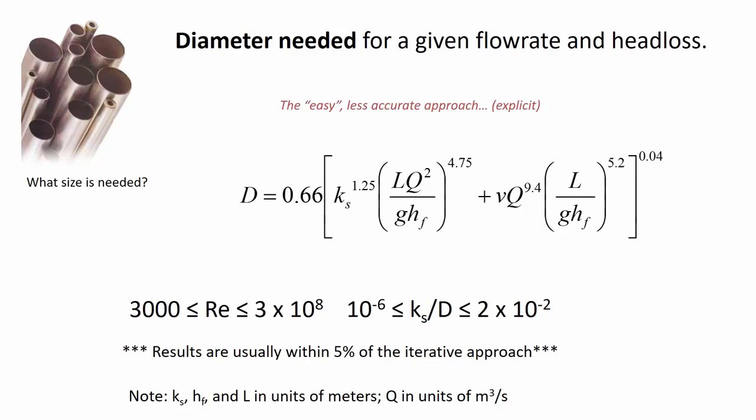Solve this formula. And it's really tough to get through it without accidentally punching in the wrong number in the wrong spot. But let's give it a shot. We have, for this one, the explicit equation. Remember, the roughness, K sub s, is 0.00026 meters.